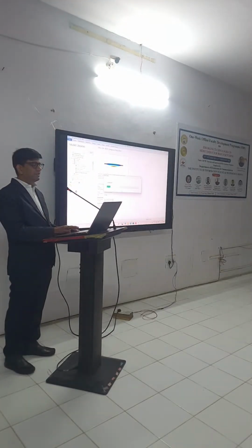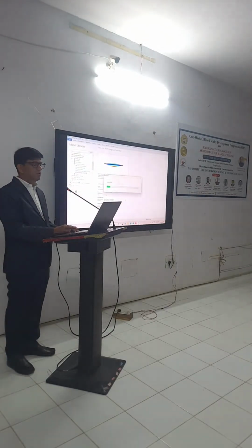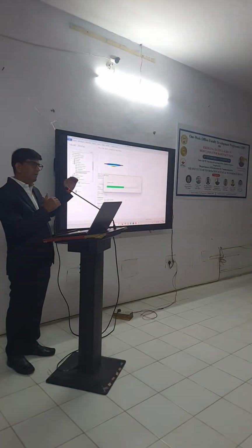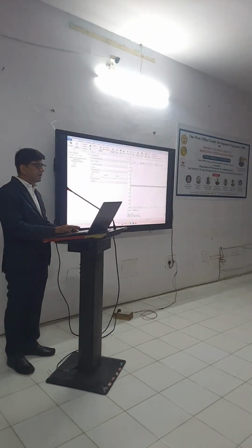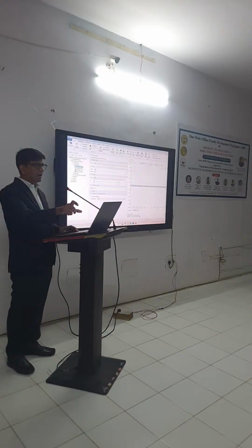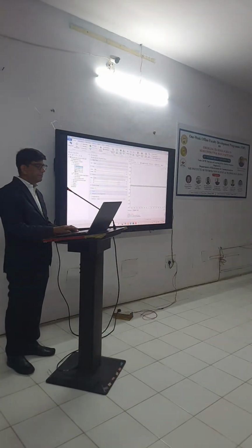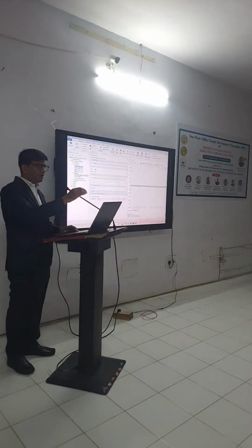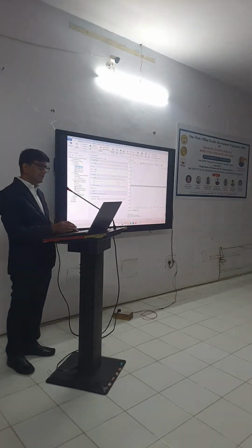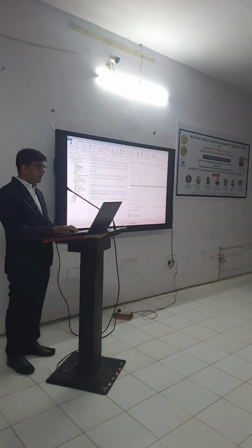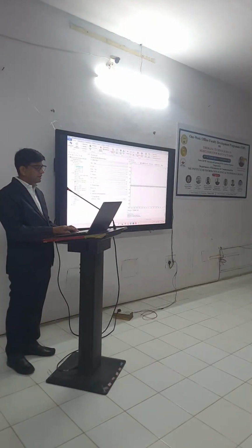Once I see this, I can learn how to apply different physics and how to apply materials. See, once you go here you have a geometry. How do you build the geometry? You can click here to set what your width and height of the device should be. Then how to define the material, so you can have an idea. Then how to define physics. Here you have a boundary condition, and you can easily understand how to define it by opening the particular model, and then how to define the meshing.